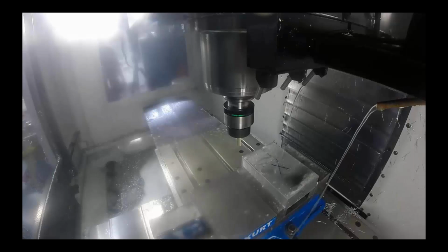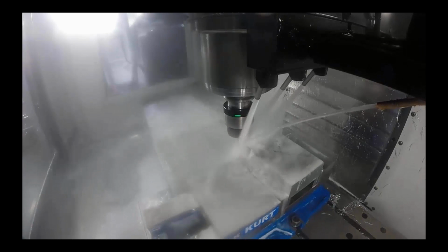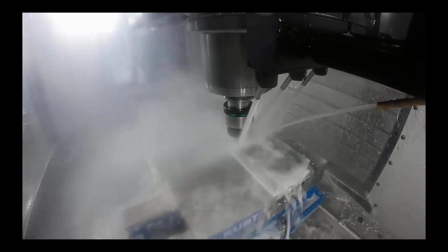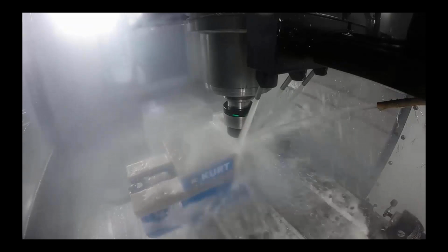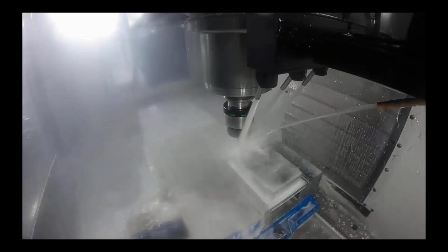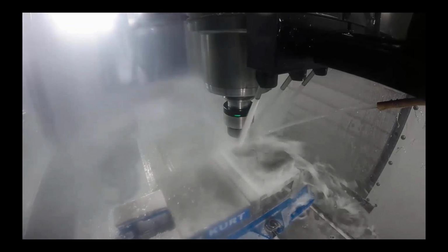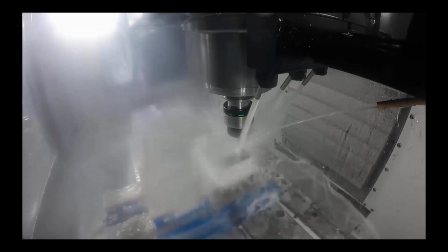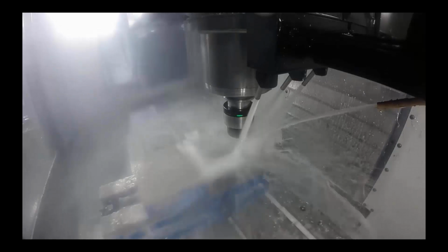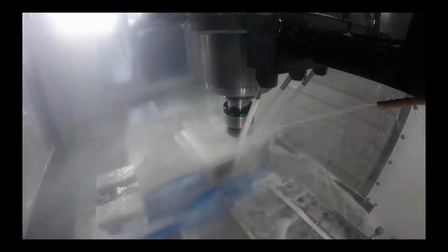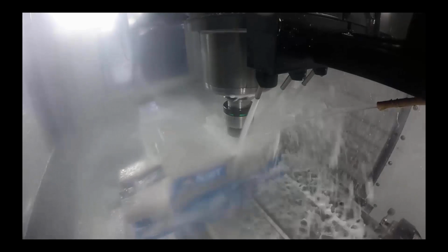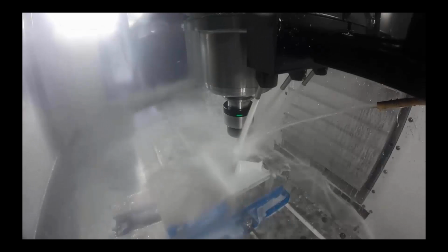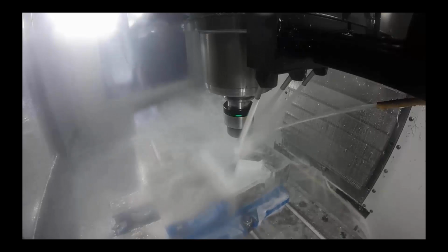Here's a quick video that highlights and shows you some of the capabilities in this area. This is a large industrial CNC milling machine that was programmed using a toolpath generated from the CAM technology that we're about to show. And you can see here that using adaptive clearing, in a few seconds we can very quickly machine out or mill out large volumes of material, at the same time minimizing the chance that we're going to break tools, minimizing the wear on the tools, and minimizing the machine runtime. So we're getting the best efficiency out of our equipment.